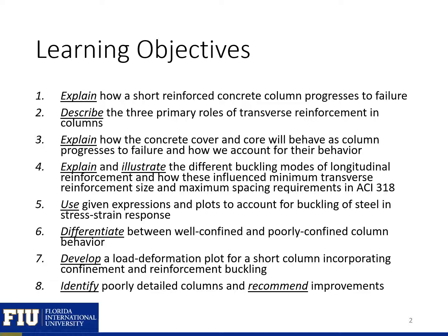Explain and illustrate the different buckling modes of longitudinal reinforcement and how these influence minimum transverse reinforcement size and maximum spacing requirements in ACI 318. Use the given expressions and plots to account for buckling of steel in the stress-strain response.